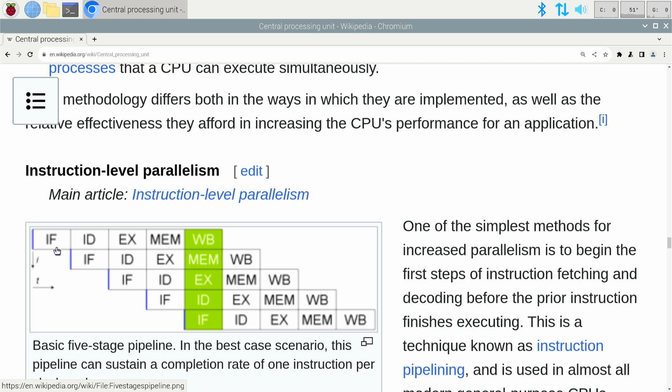With pipelining, on the other hand, these steps are sometimes carried out in parallel. While the first command is still decoding, the second command is already being fetched. Of course, this trick only works if the second command doesn't need the result of the first command. The execution of programs can be significantly accelerated by pipelining.